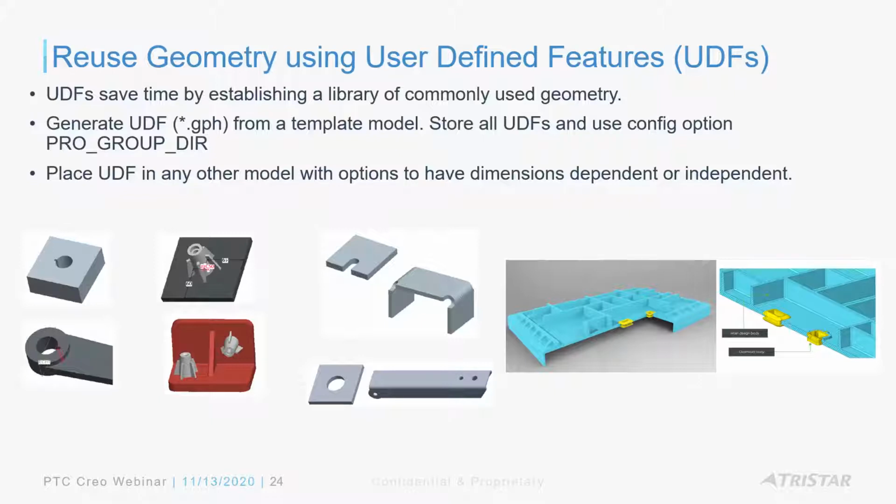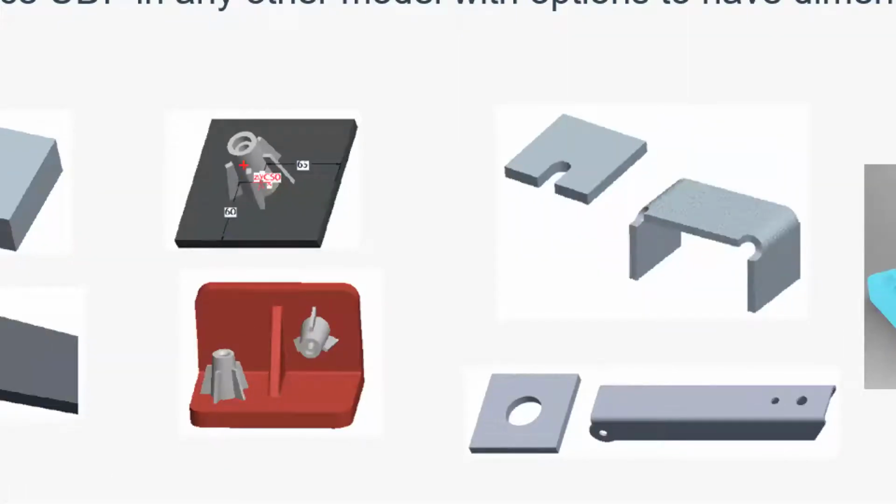Now, you might think that it has a lot of references, so there's a workaround. You could use a coordinate system, like an on-surface coordinate system like I've used here, where I've based everything off the on-surface coordinate system. So when I place it in different designs, it's easier to just select the placement references of the on-surface coordinate system, and then it takes it from there. So it's very, very useful.